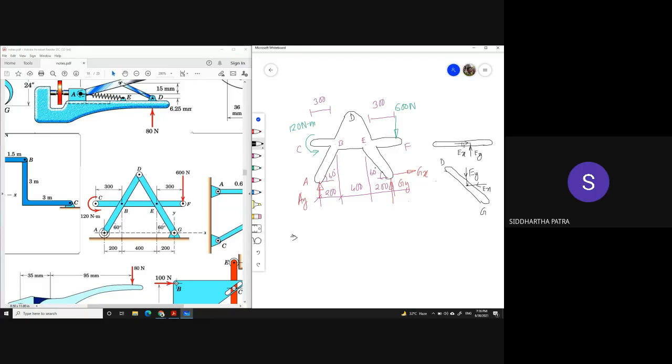When you are drawing the free body diagram of the whole structure, these two actually combine. Because when you are drawing the free body diagram of the entire structure, you are not considering the two objects to be different. You are considering the total assembly as a single unit. For example, let's take this rod right here, hanging due to its own weight.